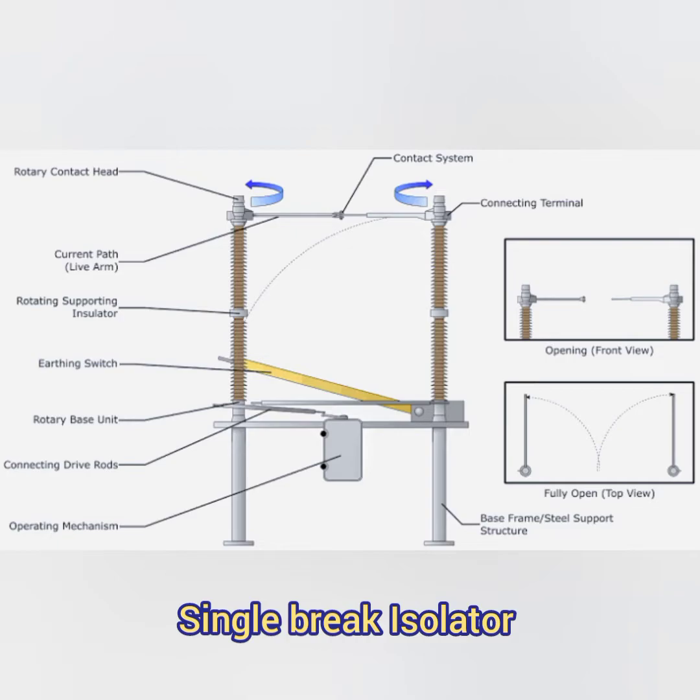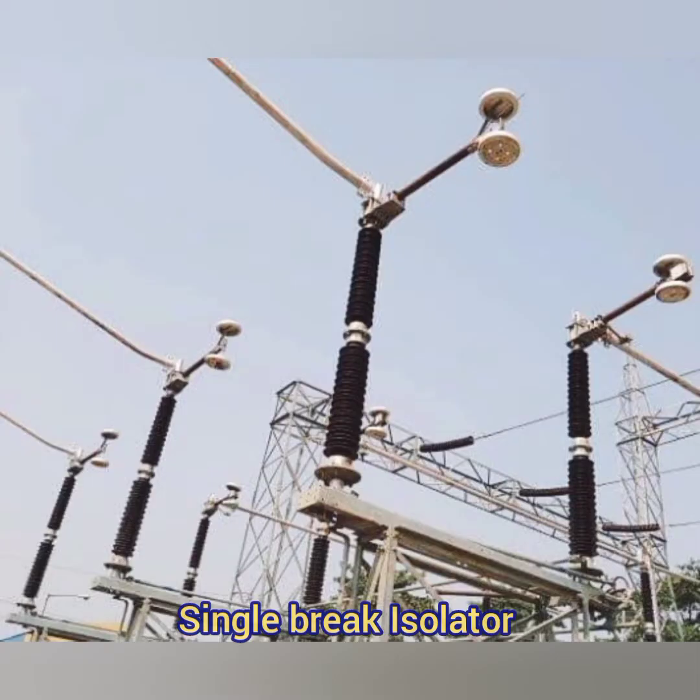This single break system consists of various parts, same as the double break system, except here the movement of the female and the male contacts is different. It has the rotating contact head, then the rotating supporting insulators, then the earth switch which is connected in parallel, then the rotary base unit which means the rotating shafts, then the connecting device or shaft connectors, then the rotating or operating mechanism. So this is an example of the single break system.